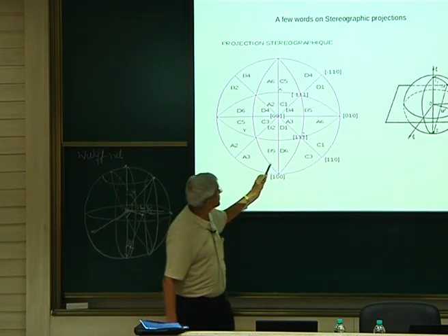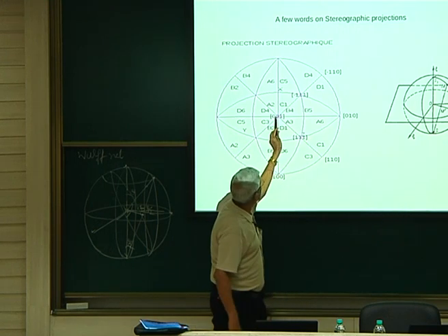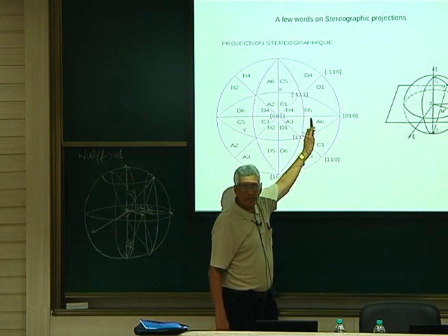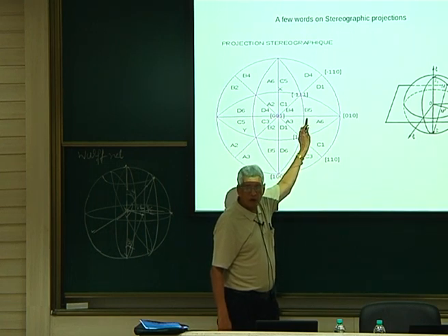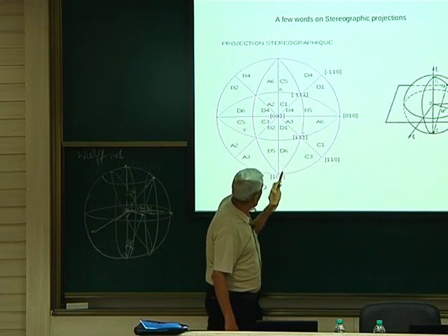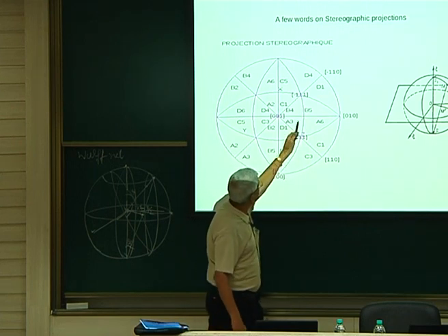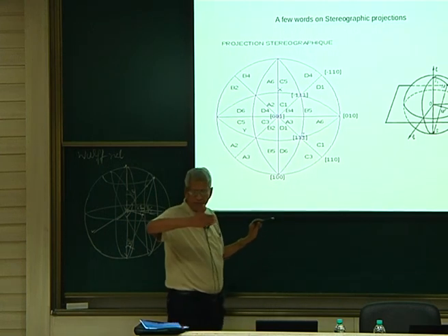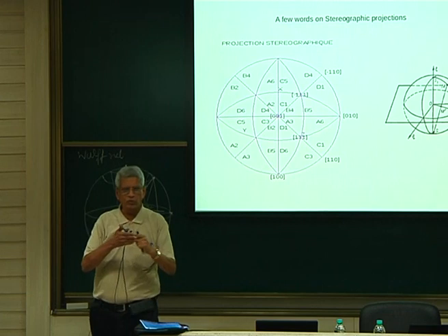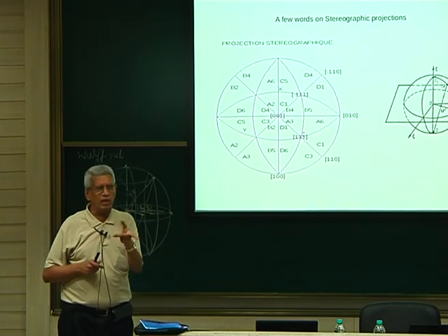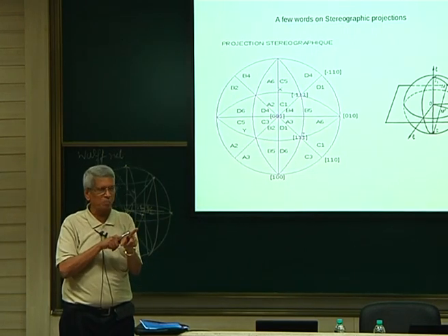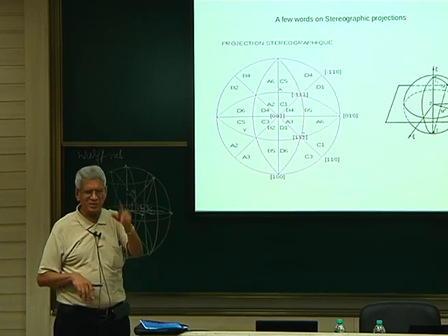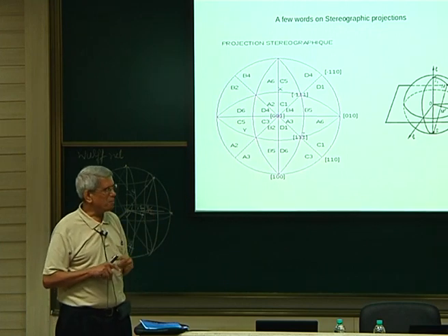Not only indexing the diffraction pattern, suppose I tilt the sample from here and bring it to another point, the 0 1 1 orientation. Then if it reaches that point, what all spots will come also becomes very clear, because you can see immediately that this orientation of this part is 90 degrees. So when I tilt that sample, the 200 diffraction spots which appear will not be rotating on the crystal, they will remain at the same place. This I will show you. I think I explained this in the first class, but I will repeat it again tomorrow and make it clear to you.